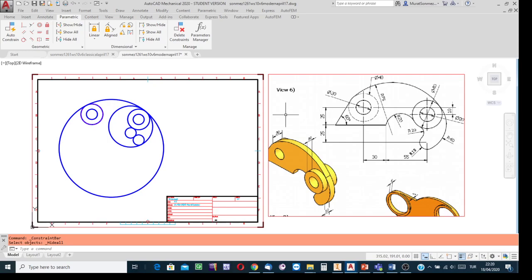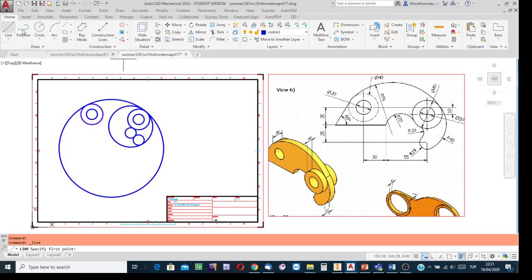And then how it is inclined. Here I'm going to use this priority. Instead of creating a dummy line and using that dummy line, after making it horizontal, as the reference for inputting this angle, first let me create this horizontal boundary, and then with respect to this boundary I can incline that tangent line. Create the line first arbitrarily.